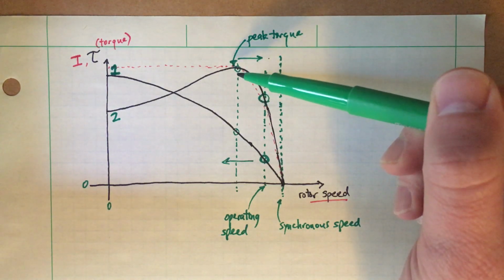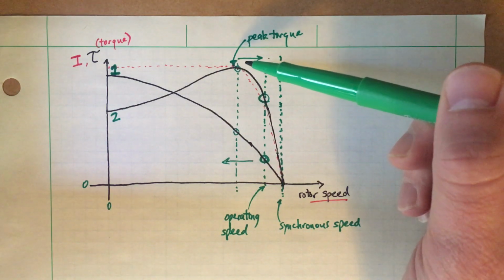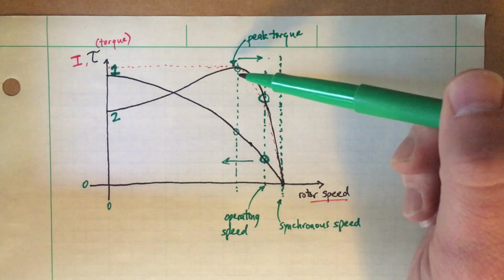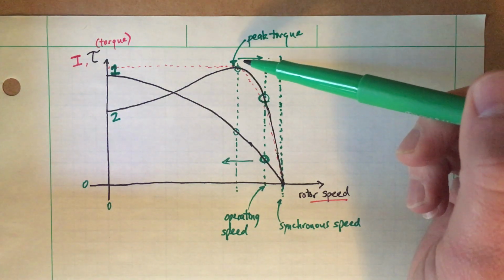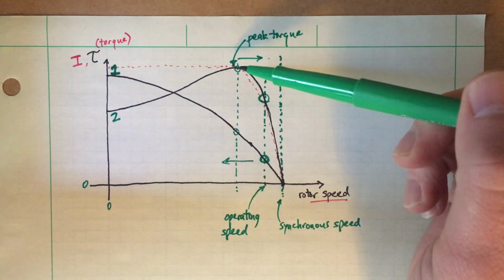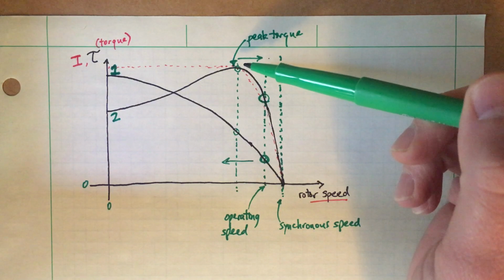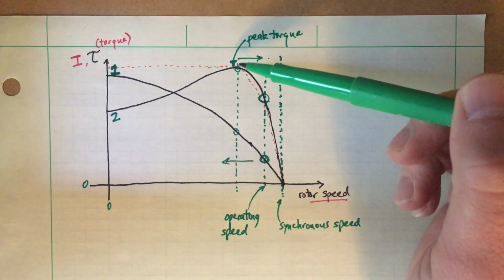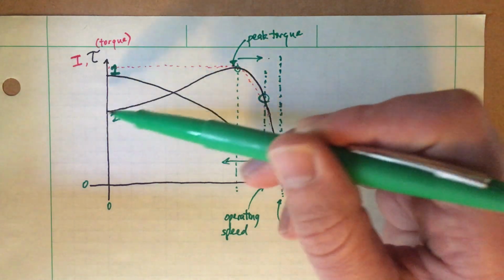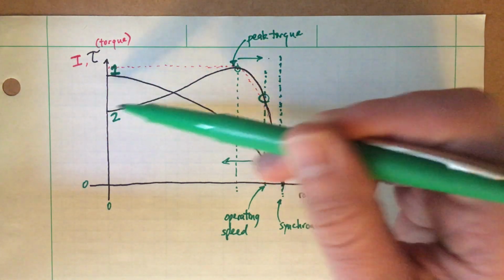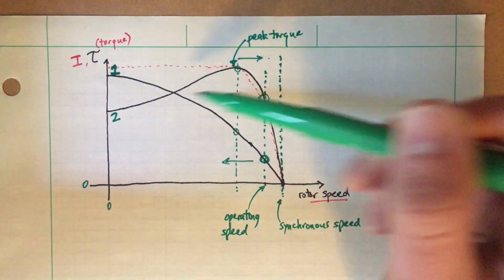If it stays on there, right, you can't get rid of the seaweed, or something is breaking and so it's not likely to go away, it's only going to get worse or something like that, well then at least the torque developed on the motor will balance that extra resisting torque and give you a chance to sort of figure something out to do about this situation before you, in this case, go down. If you go farther down in speed, well then now the torque developed by design number 2 actually goes down. Still a lot of torque compared to sort of typical operating torques, or at least comparable to it, the way I've drawn it.